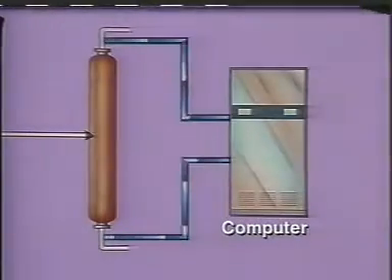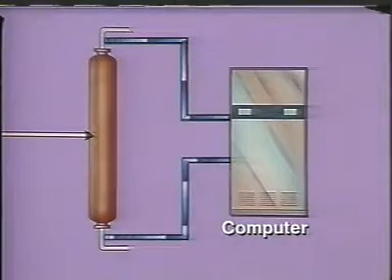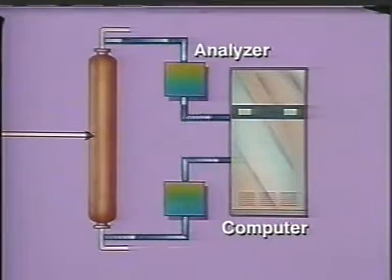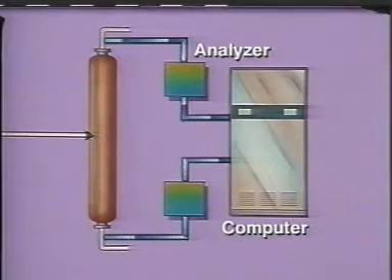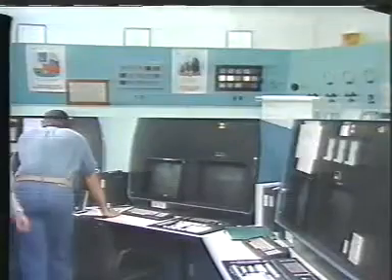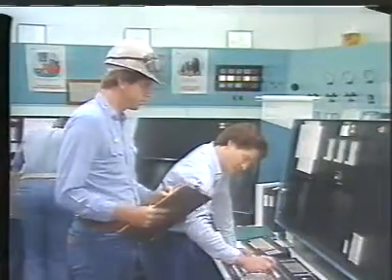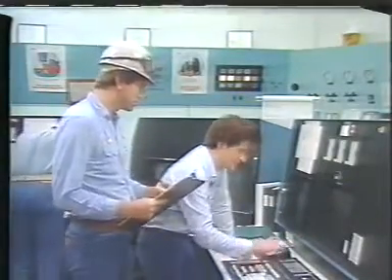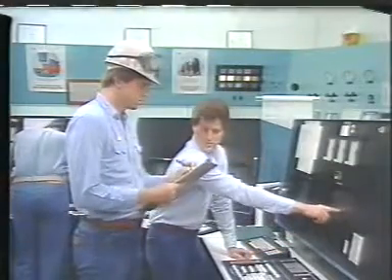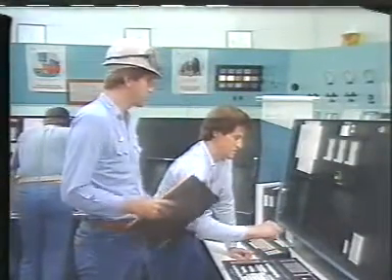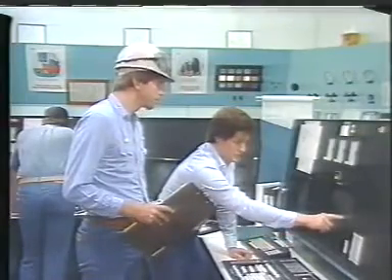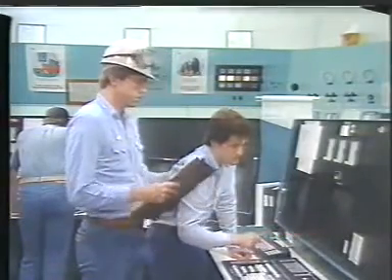More effective control of a series of towers is realized by using chromatograph analyzers in conjunction with a computer. During normal operations, a computer-based system makes closer cut point divisions than conventional instrumentation. This saves energy and allows us to recover more of the valuable components. During process upsets, the computer quickly gathers and analyzes all the important data. The computer then advises the operator what operational changes to make, or makes the changes automatically. These adjustments keep the entire series of towers operating at maximum efficiency until the problem is resolved.